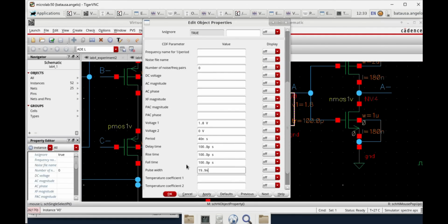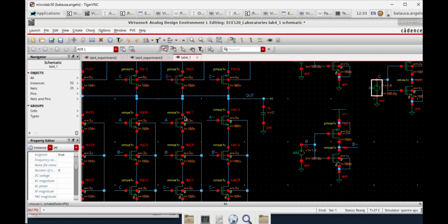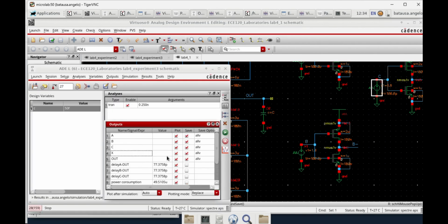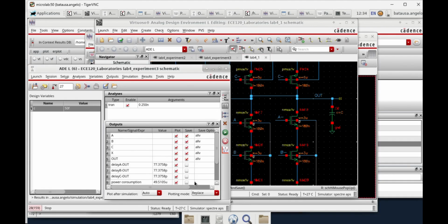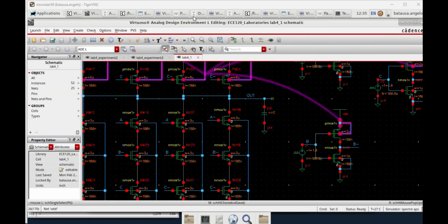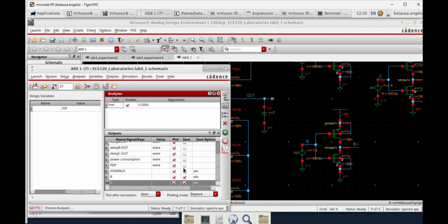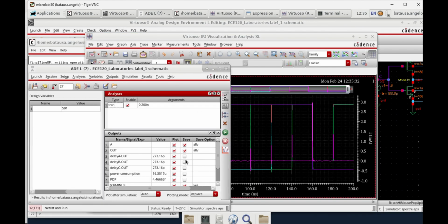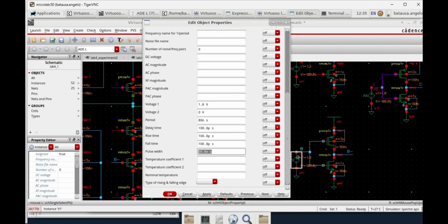Additionally, to test the static CMOS circuit, the student modified the input pattern while maintaining a fixed loading capacitance of 0.05 picofarad. The input signal frequency was increased by factors of 2 times, 4 times, 8 times, and lastly 16 times, requiring adjustment to the signal period and pulse width accordingly. Since the frequency and period are inversely related by the formula period equals 1 over frequency, the period for each case was divided by the respective frequency multiplier. As a result, the pulse width was also adjusted proportionally to maintain the same duty cycle.